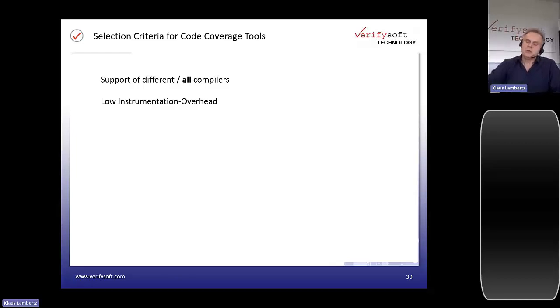Because normally when you are working with embedded software, you should check on the target. You should measure the code coverage on your embedded target. If you can do this, the standards request that you do it. Not everybody knows that, but the standards request that, and with a good coverage tool like Testwell CTC++, you can check the target.